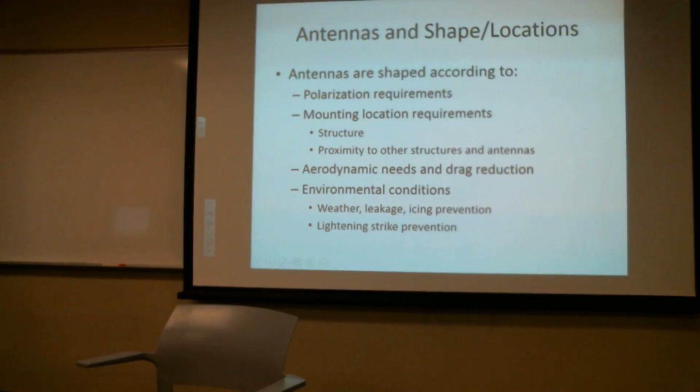So the other thing is, if I put the antenna next to a big tall building, or the vertical stabilizer, or pretty much anything else, the way it emanates electromagnetic radiation, it's going to cause echoing and all kinds of weird things. It's just like if I took my pond and had a big wall over here in the middle of it and started dropping my rock in there. It's going to radiate out until it hits that wall, and then there's going to be reflections coming back, and they're going to interfere with my original waves where they're bouncing into each other.